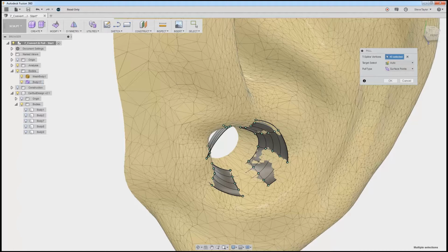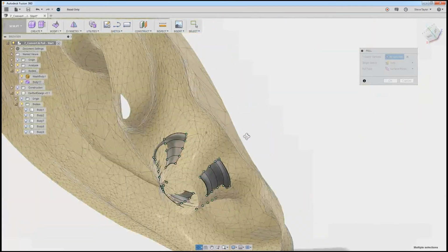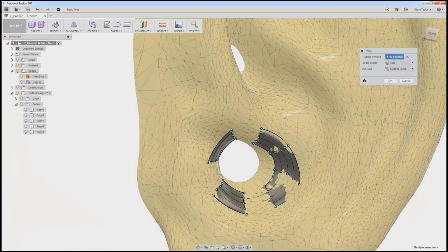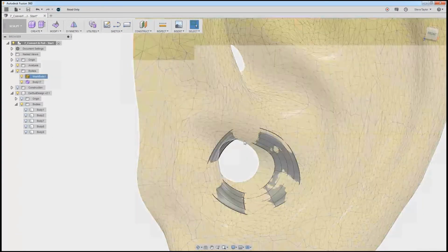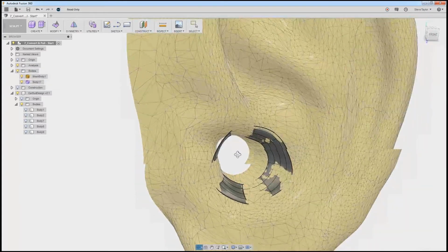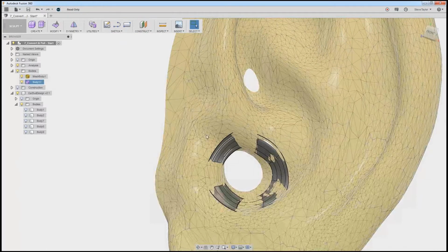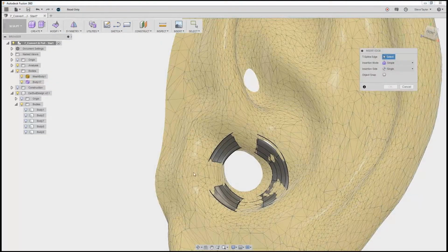It's not done a bad job really, but you can see the gaps. You can actually see the gap there. It's brought it in a little bit tighter in there, and there's a bit of a gap there. So okay, it's now snapped that in. There's that gap that I want to get in. I'm going to insert an edge here. So if I modify, insert edge, if I select,